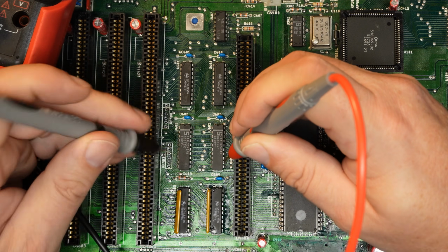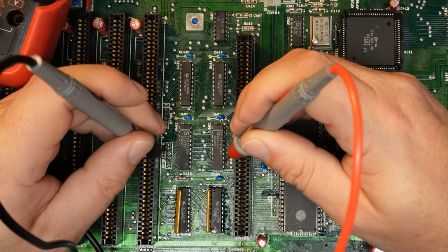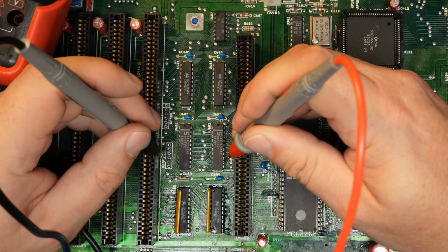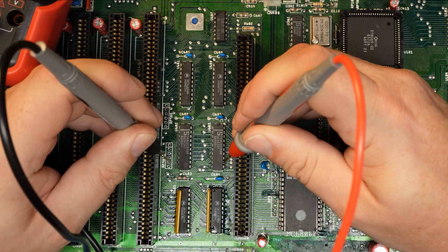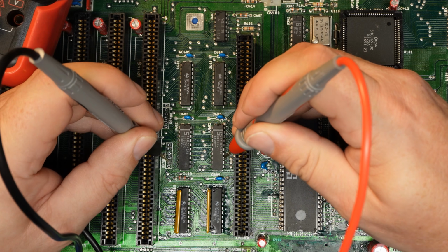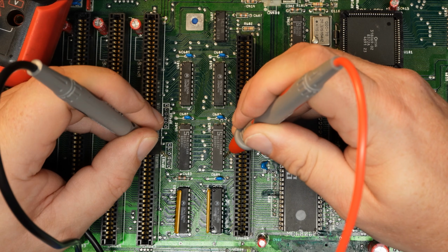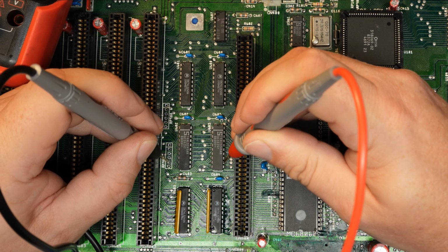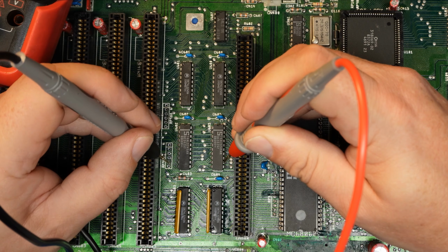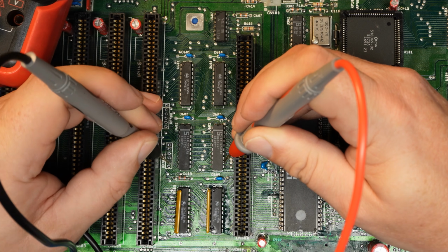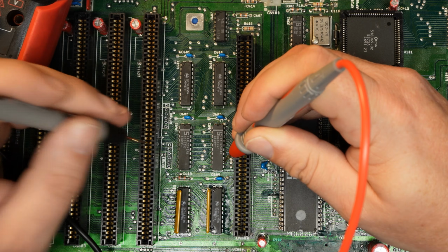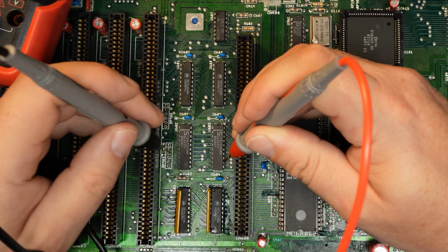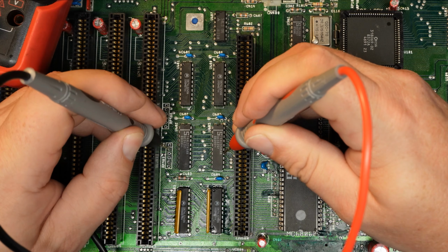I don't believe this. I must have nicked something there while trying to cut those resistor packs out, because it seems I've damaged the connection at that point. You know, that's okay there, and that's okay there, but that's not okay if I poke into the trace though. It is. So yeah, maybe don't try and cut them off.